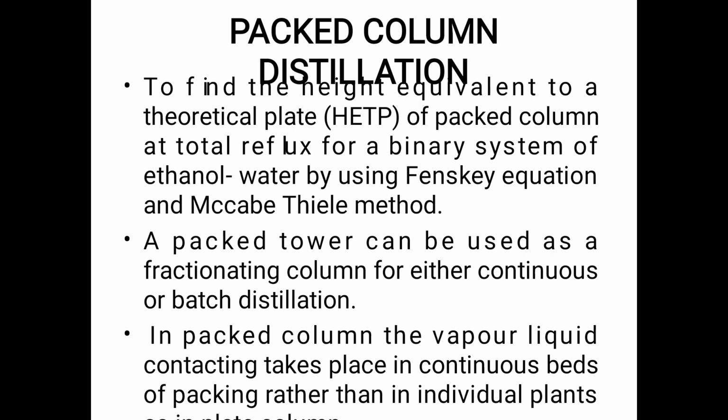To characterize the packed distillation column, we have to calculate the HETP, that is, the height equivalent to a theoretical plate. It means the height of a theoretical plate. It is determined in a packed column at total reflux for a binary system of ethanol and water, by using the Fenske equation and the McCabe-Thiele method.